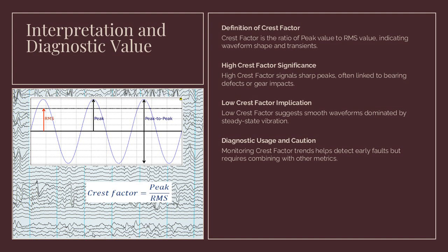Conversely, a low crest factor suggests a smoother waveform dominated by steady-state vibration. Monitoring crest factor trends can help detect early-stage faults before they escalate. However, interpretation requires caution, as changes in crest factor may also result from variations in load or operating conditions. Combining crest factor with other metrics ensures accurate diagnostics.